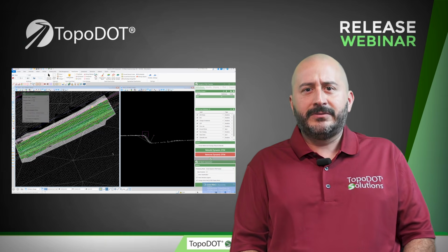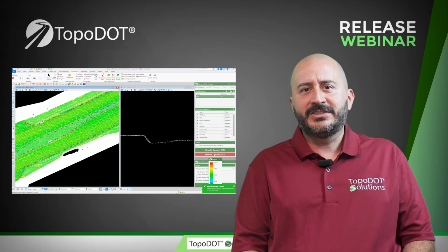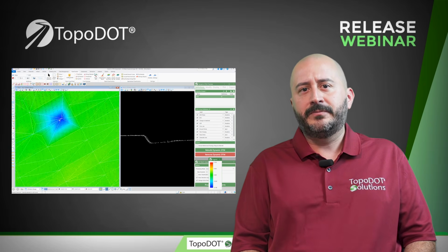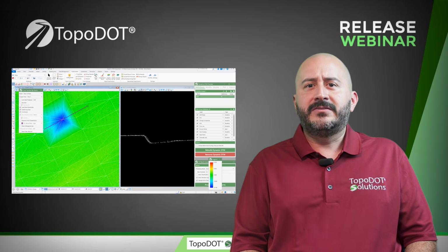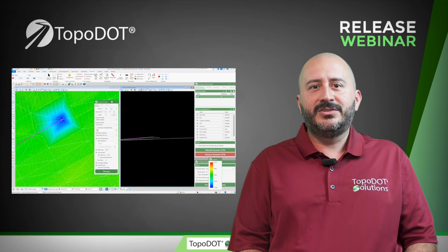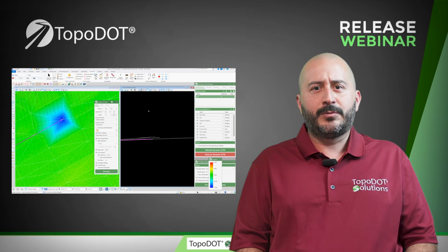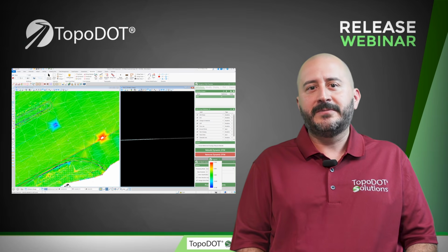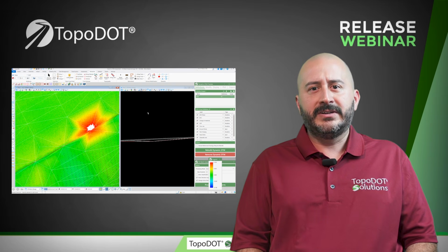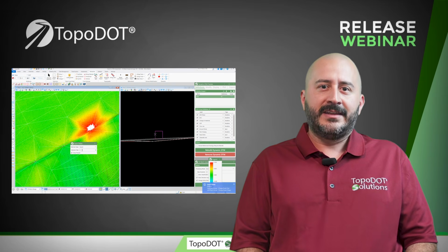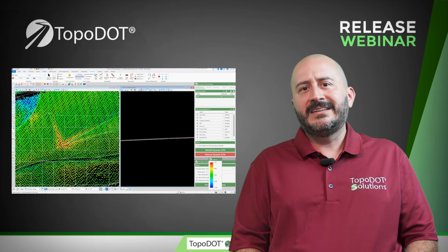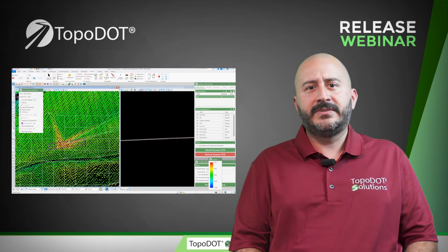But we didn't stop there. We've also completely rewritten the 3D Mesh Assessment tool with some powerful new capabilities to complement your DTM workflow. Specifically, you can now run the 3D Mesh Assessment directly on the Dynamic DTM. There's no longer a need to waste time plotting or exporting the mesh element just to check your work. It's a massive time saver that allows you to quickly adjust your line work and instantly rerun the assessment to verify the results. Additionally, we've added classification support, so now you can quickly isolate and find specific point cloud regions that deviate from the mesh.